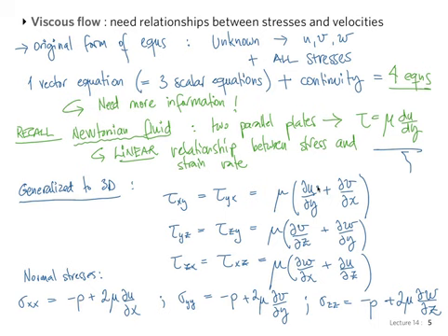Use the continuity equation where you have, for example, du dx plus dv dy plus dw dz. Then you can use the continuity equation because that's equal to 0, and that cancels out, and things simplify beautifully, and you get the full Navier-Stokes equations, which I will write without further ado. We will just write them out. Now, for the case of Newtonian fluids, right?